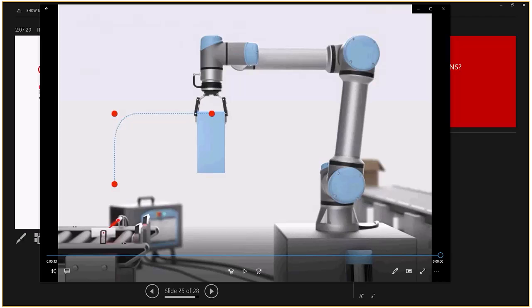If you want to change the speed in the moves, make sure that all the moves and all the waypoints in that move are supposed to go at that speed, because otherwise the robot's going to go up, come down, and when it moves it's going to hit things. Also, making the robot move faster is going to be working on your joints and things like that too, so your maintenance and services are going to come sooner. So that's another thing they rather not have you do.